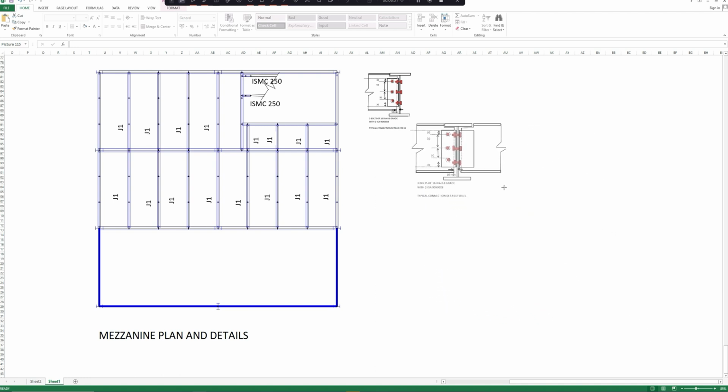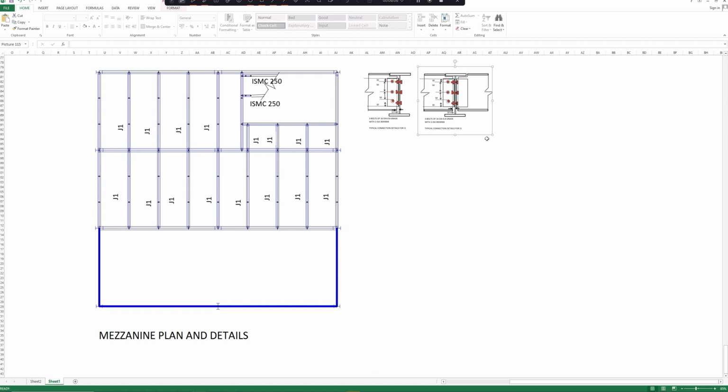When joists are connecting from the 2 sides, it is the same joist. So when the structural GA is provided to the fabrication detailer, he will take appropriate detail as required. In addition to this, you have to provide the connection detail of the stringer.